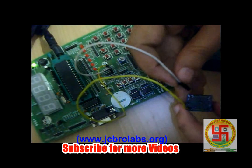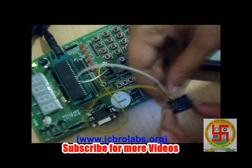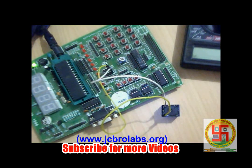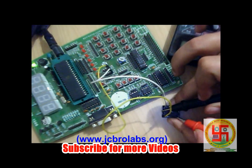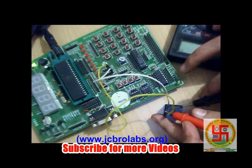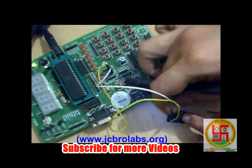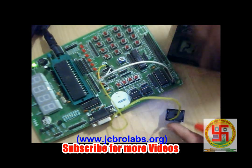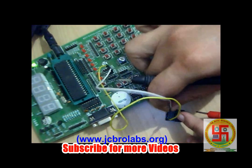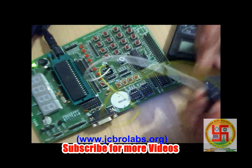So you might hear a sound as soon as we connect the supply. This sound indicates that as soon as we have connected the supply, other connections have been made, and this LED and this relay are turned on. Now if we check the continuity from these 2 pins, these are no longer connected, and now this middle pin is connected to this other pin. So if we release the power supply, these 2 pins are connected, and as soon as we connect the power supply and it turns on, these last 2 pins are connected now.